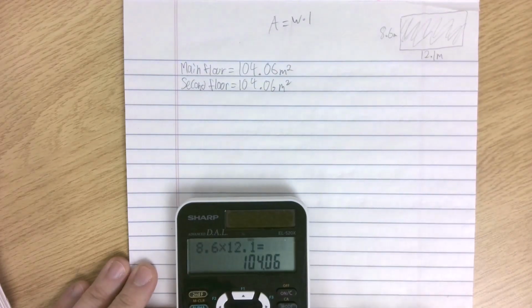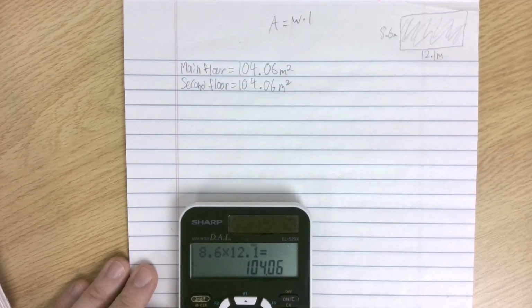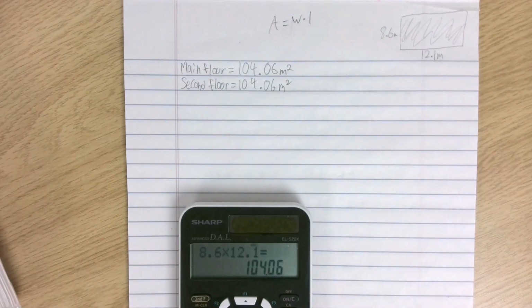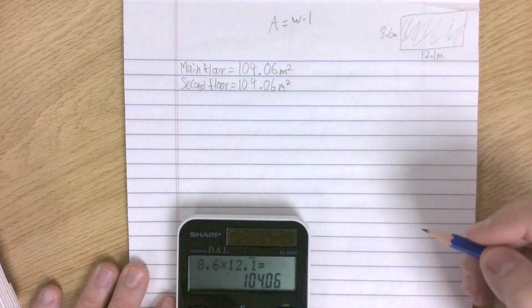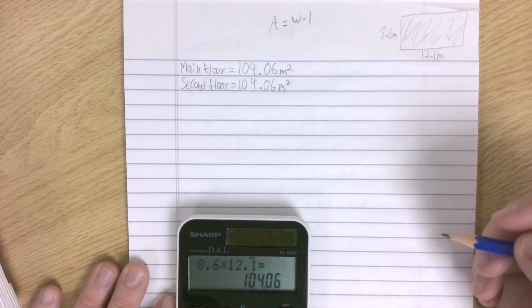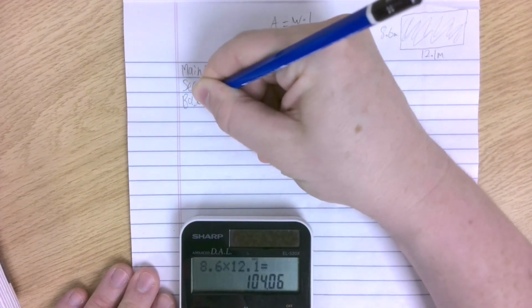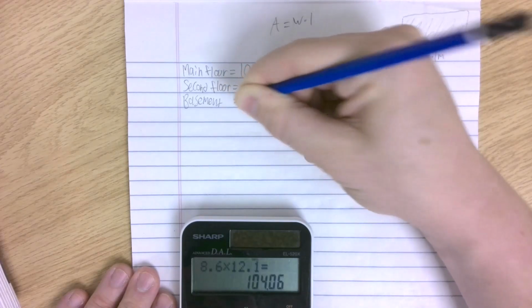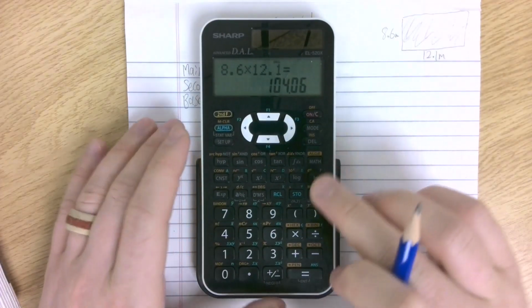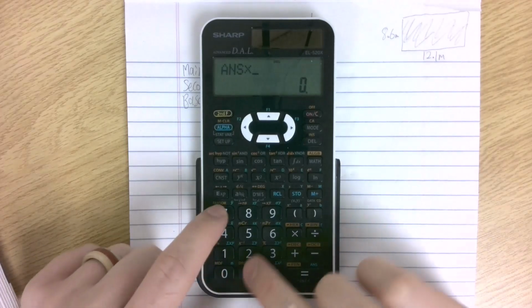And then the question tells me the basement is the same size, so I don't need to account for any frost walls or any extra temperature or other requirements that you might put in a basement. So the basement is the same size, but 8110 tells me to take 75%. So my basement is going to be equal to 104.06 times 0.75.